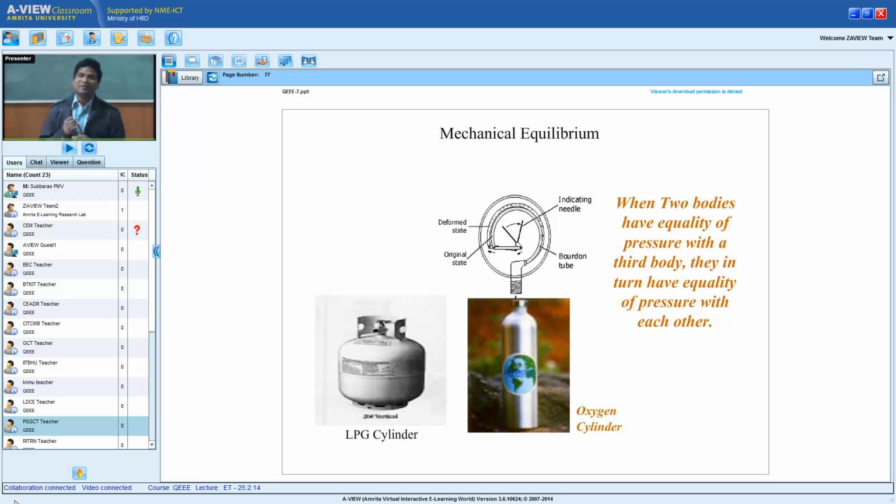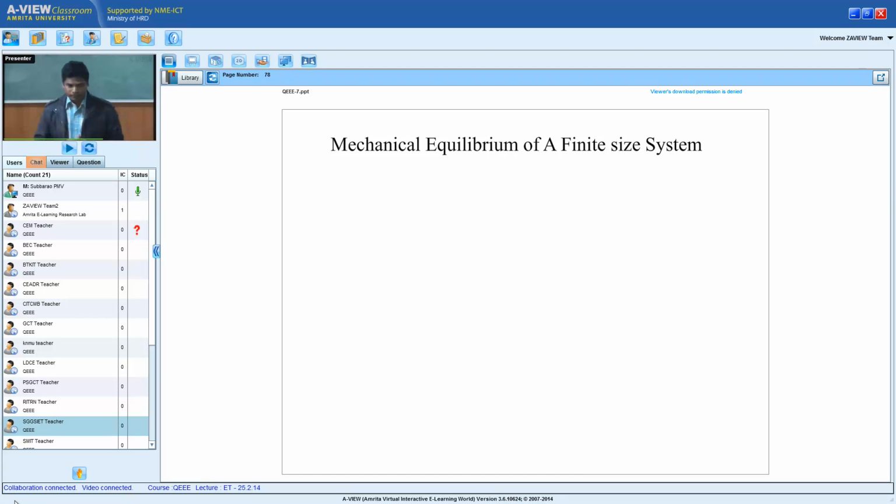So a mechanical equilibrium can occur when the pressure is the same, or the force is the same, or the torque is the same. That's how the zeroth law doesn't talk about every equilibrium as a law. Why? There are many ways mechanical equilibrium can occur, but thermal equilibrium occurs almost in a single way. So you learn from the zeroth law and implement it for other parameters. You can measure force, pressure, torque, or anything else required for mechanical equilibrium. So that's how it works with mechanical equilibrium. Any more questions?